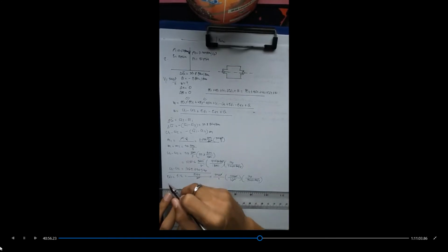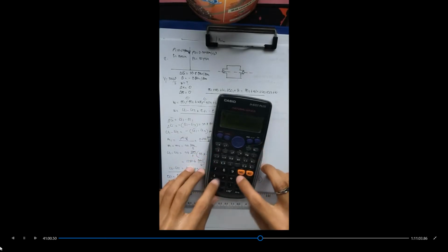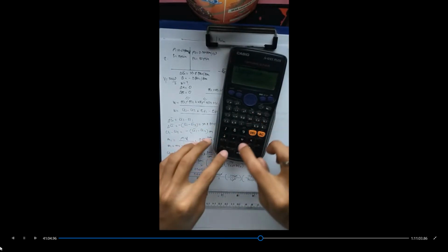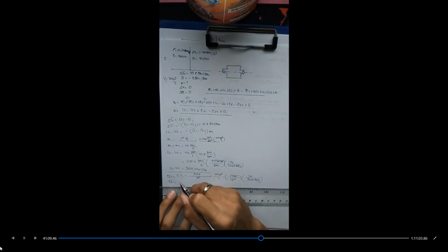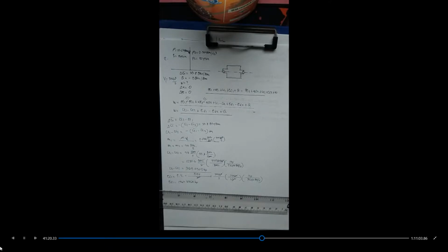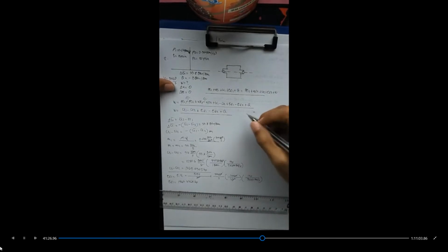Just like that, we get our flow work 1 by multiplying 15 by 500 by 144, then dividing by 550. It is 1963.6364 horsepower. Next we solve for our flow work 2, but in order to solve for it, we need to solve for our volume 2 first, and I'm just going to put it here on this side.